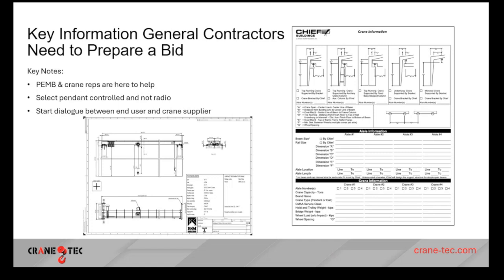I'd like to interject here. It's very simple for a crane manufacturer to keep the cranes out of each bay. So electronically, we just put electronic eyes on the cranes, and we can set how close those cranes can get to each other.